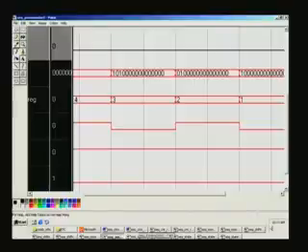This is a general question. You talked about always at positive edge, negative edge. How do you go about doing level triggering? The level is the same. I mean, you sense the level, immediately take action. It can be within the sequential circuit or outside it. If it is outside, you can use an assign statement, a mux statement you can have. If a particular level is 1, immediately let the output change using an assign statement.